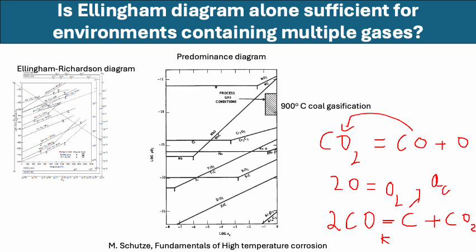So that is what is there in this axis, this is the activity of carbon, and we can determine the activity of oxygen, that is the partial pressure of oxygen. And then for each of these conditions, for a given alloy which might contain all these elements which are oxide formers, this is for different oxide formers such as zirconia. So above this line we have zirconium oxide that is stable, but below this line zirconium carbide is stable. This is one example that is given.